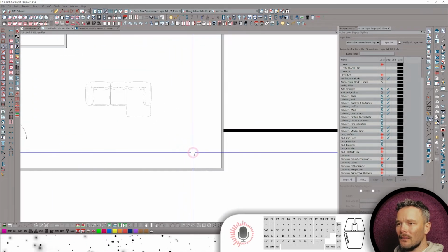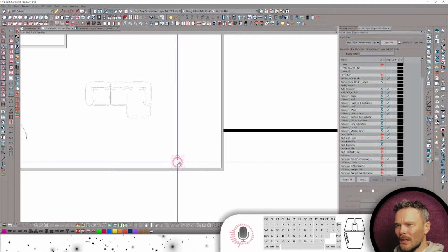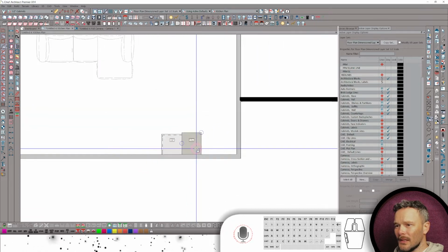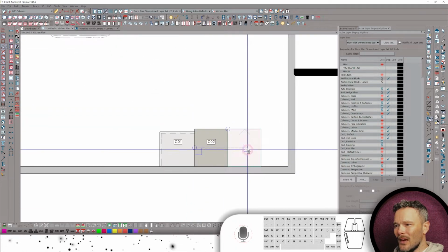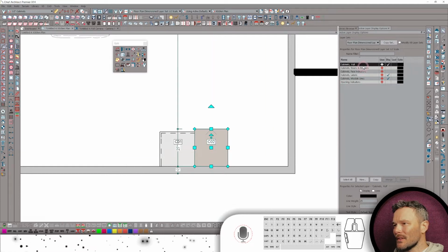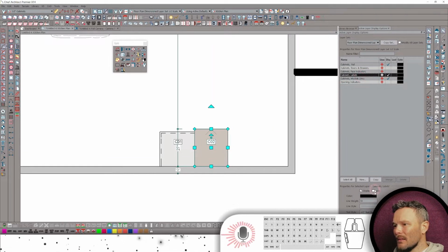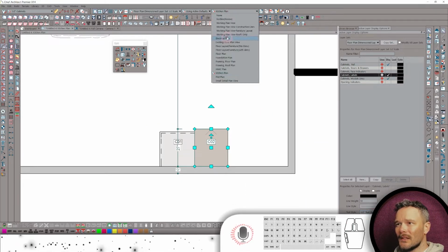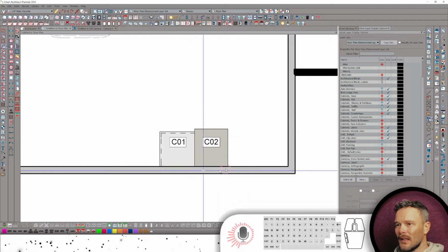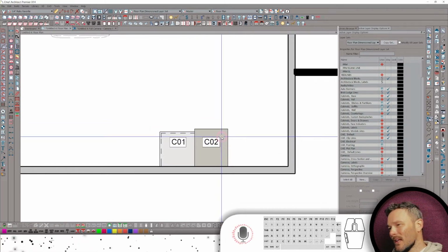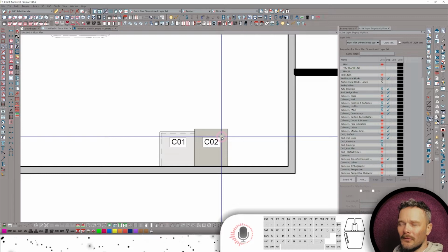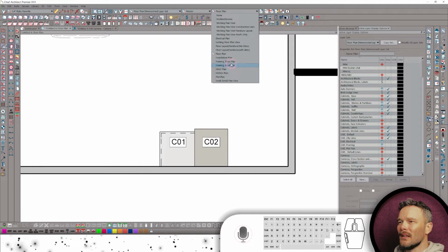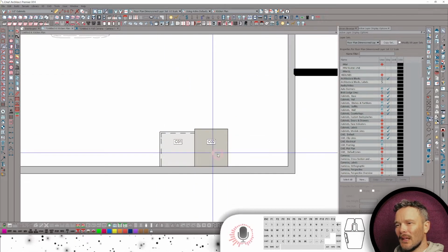Let's go ahead and take a look at my cabinets. I'm going to drop a cabinet in here. We'll actually drop in a tall cabinet in here. You're going to notice with the kitchen plan that it's set to a 1/2-inch text style in these labels. So you can see here underneath cabinet labels, you're going to see 1/2-inch text style is by default. If we switch to something like our floor plan, you're going to see those labels get pumped up. Now, if you're like me, you might want to actually turn the labels off in the floor plan, but I leave them on just in case that you may want them. So I like to turn them off because I always show in my kitchen plan my labels.